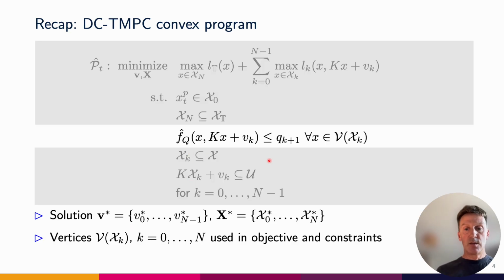So this relaxation to inequality constraints allows a convex approximation of the original nonlinear programming problem simply by linearizing any concave terms in these inequalities. Note that we're not linearizing all of the inequality, just the concave parts. The relaxation also allows us to introduce explicit handling of uncertainty in the system model in terms of disturbances or unknown parameters, provided we have bounds on these disturbances or unknown parameters.